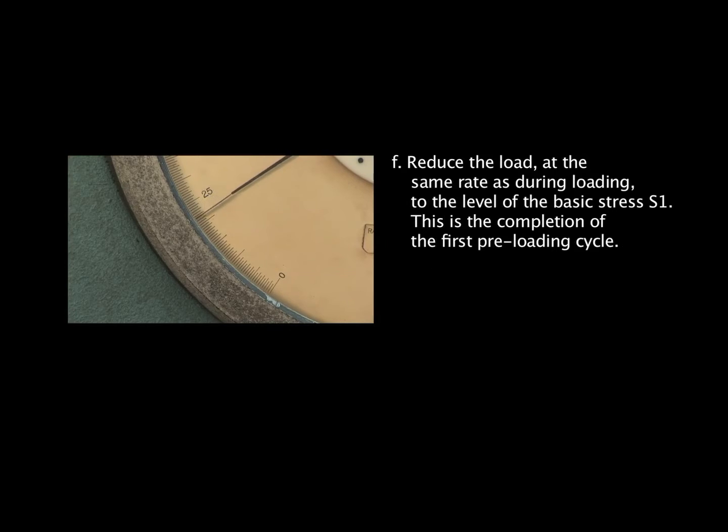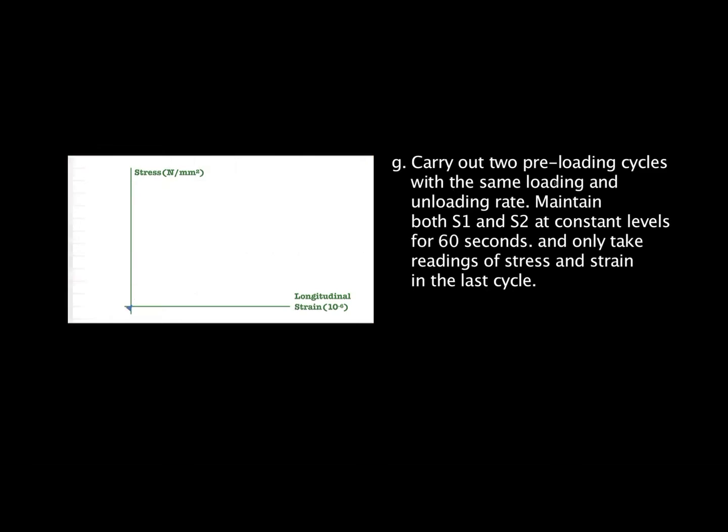F. Reduce the load at the same rate as during loading to the level of the basic stress S1. This is the completion of the first pre-loading cycle. G. Carry out 2 pre-loading cycles with the same loading and unloading rate. Maintain both S1 and S2 at constant levels for 60 seconds. And only take readings of stress and strain in the last cycle.